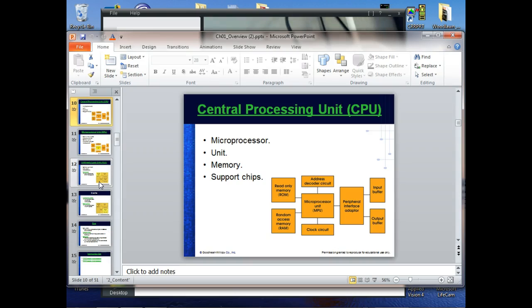And then the microprocessor has RAM and ROM, but the ROM can be different variations. From our point of view, ROM is ROM, whether it's EEPROM or double EEPROM. It's something that we right now don't have the ability to change. It's read-only, non-volatile. The RAM, which is random access, is a volatile memory, which means it can be lost. If we turn power off, it's gone. So the big thing is how much memory you have.